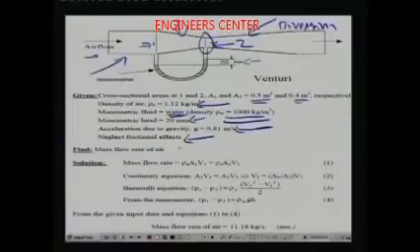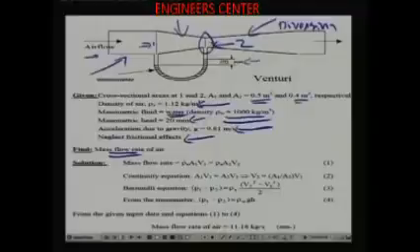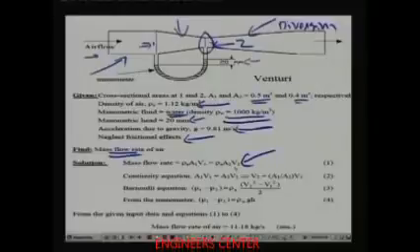First, what is the required output? We have to find out the mass flow rate for this venturi, which shows a manometric head of 20 mm. The equation for mass flow rate is rho A V, that is, mass flow rate at any point is equal to rho into the cross sectional area at that point and the velocity at that point. So, you can write this expression for mass flow rate, and from the continuity equation, nothing but the conservation of mass equation, A1 V1 is equal to A2 V2, because we are assuming the fluid to be incompressible. So, rho A at any point is constant.